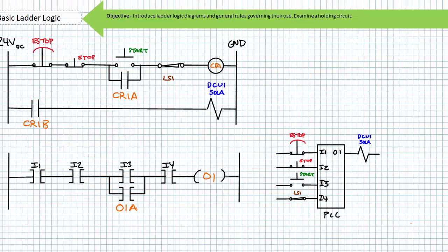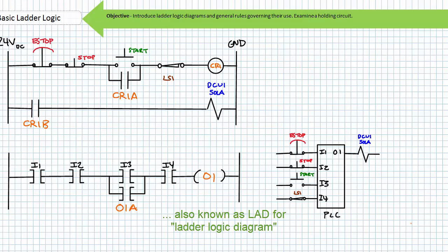For those concerned about the relevancy of learning traditional hardwire relay-based ladder logic, take heart. PLCs are commonly programmed using something called RLL, relay ladder logic, a method astoundingly similar to traditional hardwired relay-based ladder logic. This is to suggest that you are learning 2 skills at once. An understanding of ladder logic diagrams is essential to your understanding of the function and troubleshooting of all modern electrically controlled systems.